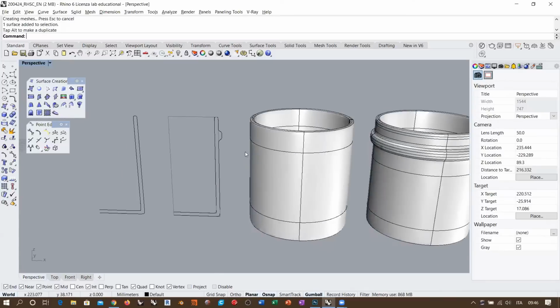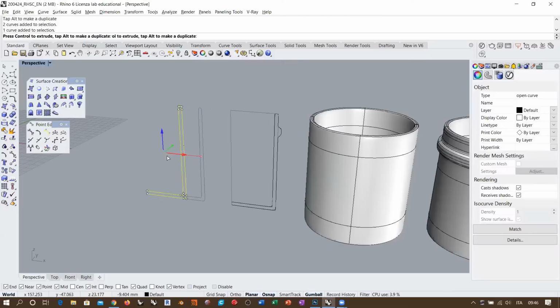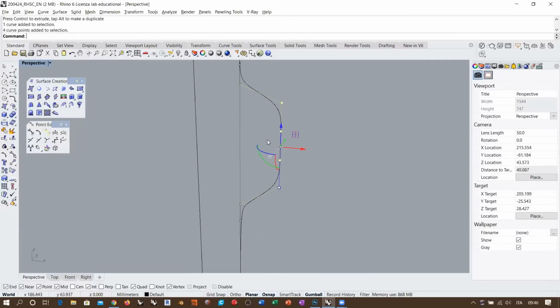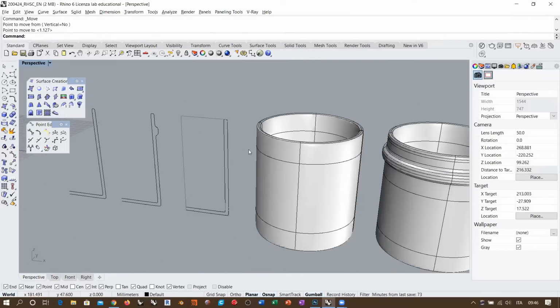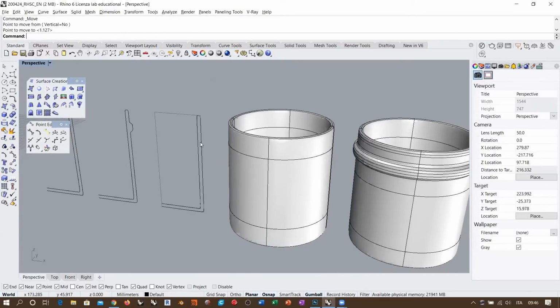So for example, the other alternative that I have is this. Let me further move this, and let me save a copy of this profile. I could also take these points here and move them back, move them perpendicular to my original ray, and leave them here. Once I have the topological condition, we know that this will be taken into account during the revolve command, because we saw that the revolve maintains the topological complexity of the profile.